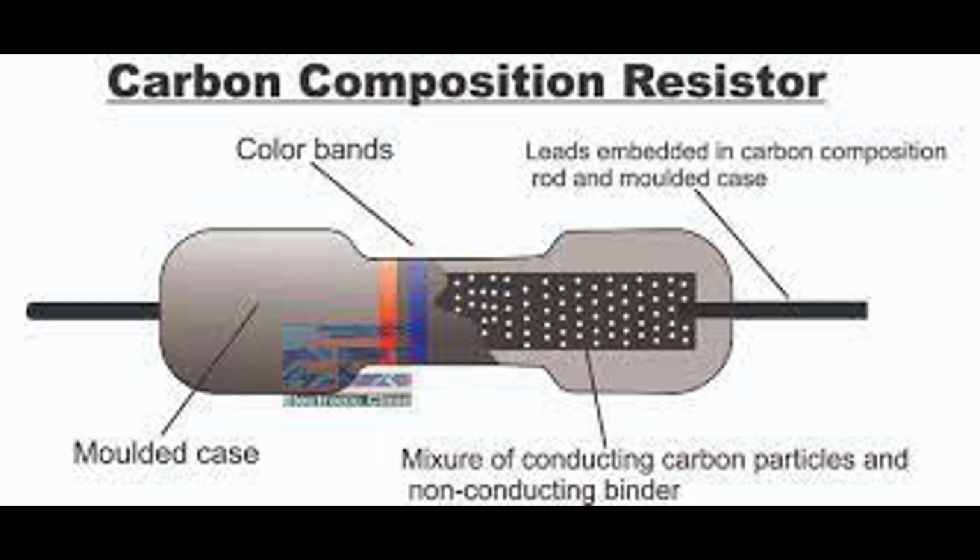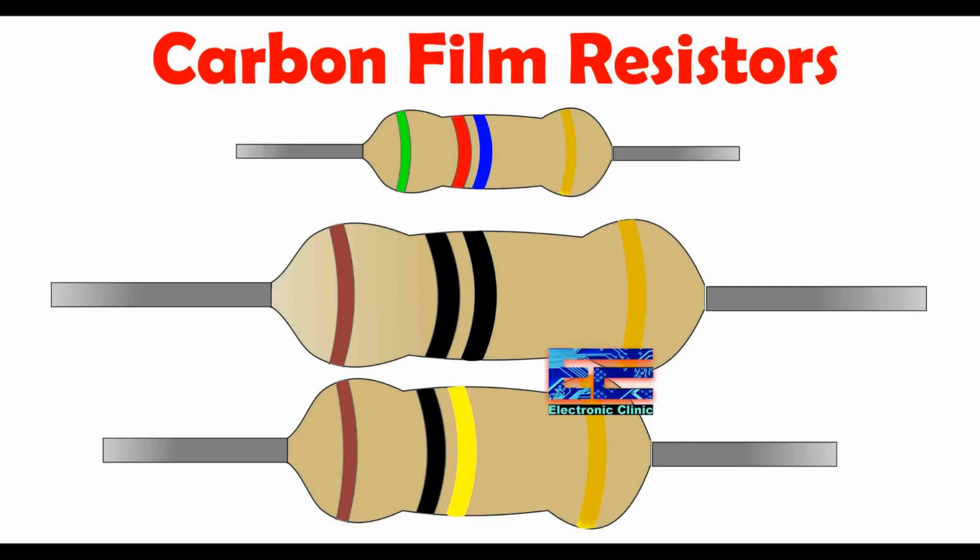Temperature stability: temperature can significantly impact the resistance of a resistor. Stable resistors are designed to have a low temperature coefficient of resistance, TCR, meaning that their resistance changes only minimally with temperature variations. Low TCR resistors are preferred in applications where temperature fluctuations are common. Long-term stability: resistors should exhibit long-term stability, meaning their resistance values do not drift significantly over the life of the component. This characteristic is especially important in applications where the circuit's performance must remain consistent over many years.